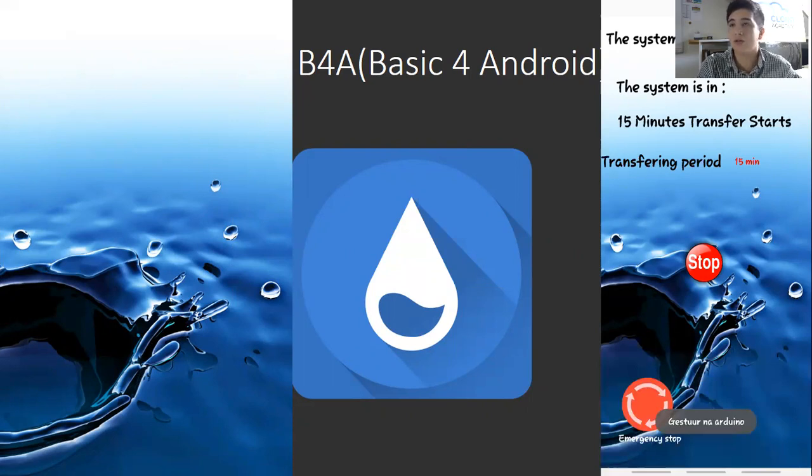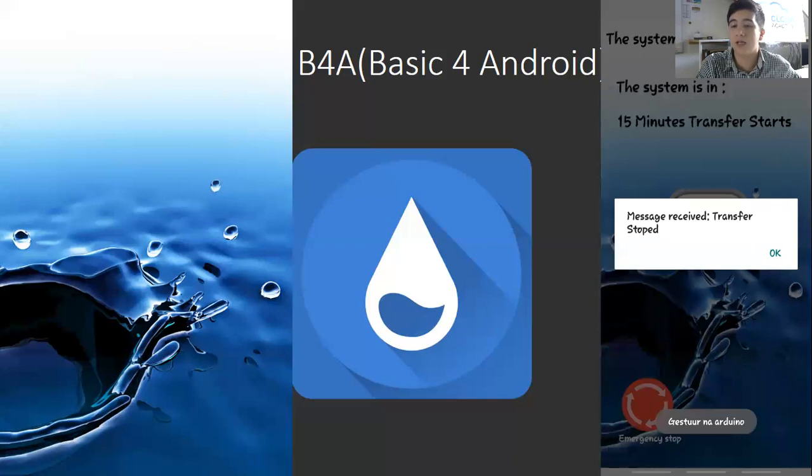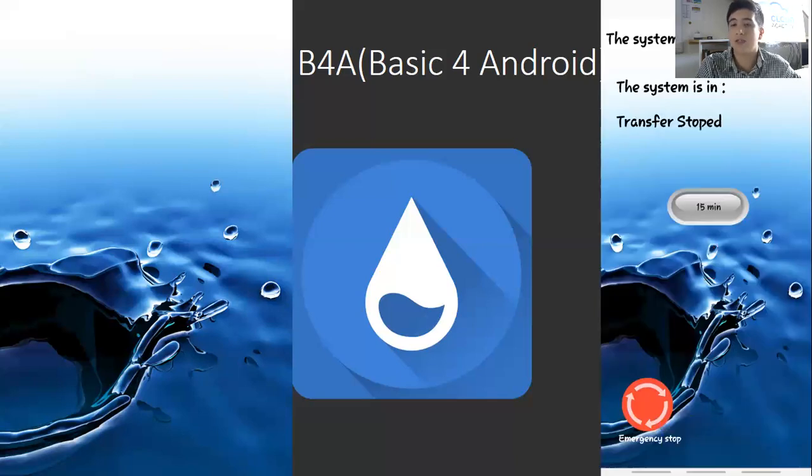This transferring is not transferring from the dirty tank to the clean tank. This is transferring clean water to a secondary house with a smaller tank. And I'm using the timer because I can't put in a float switch because the destination of the house is too far from the tank's location. So if you click the stop button, a message box appears and it says the transfer is stopped. So we say okay, and it says the system is in a transfer stopped mode.